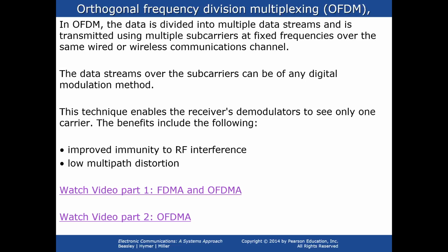Now, previously we have shown that in a wireless channel, due to multipath propagation, we face delay spread and inter-symbol interference. We have also discussed how its effect can be reduced by increasing the symbol duration, and how guard periods were used to eliminate it. But abrupt changes in the time domain during the transition from symbol to guard period cause intercarrier interference in the frequency domain and disturb the orthogonality between subcarriers.